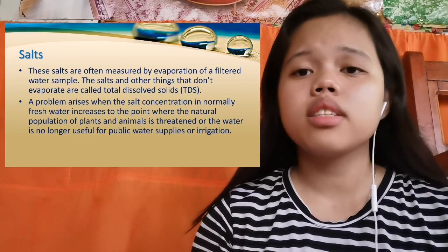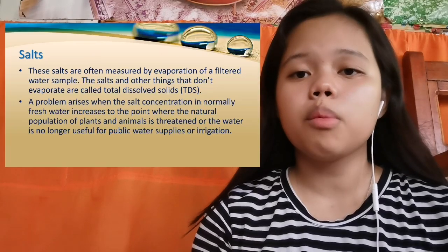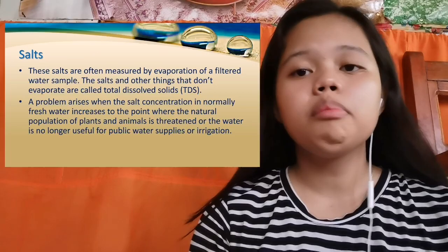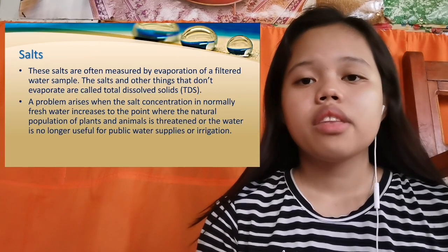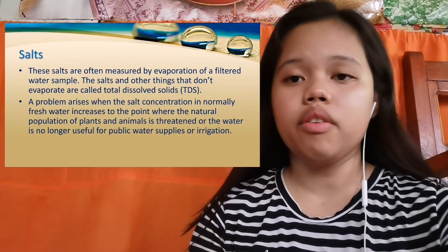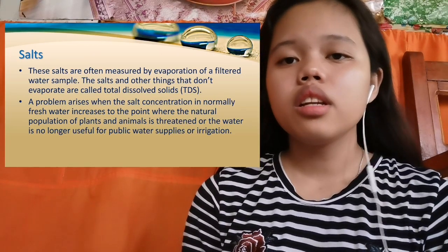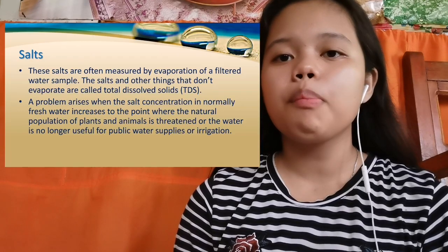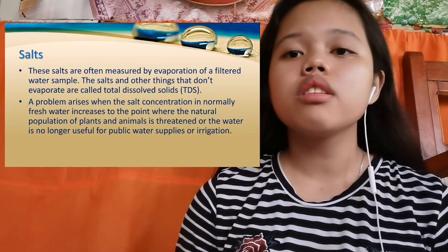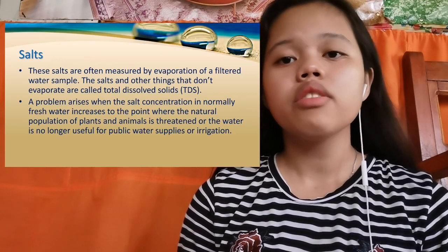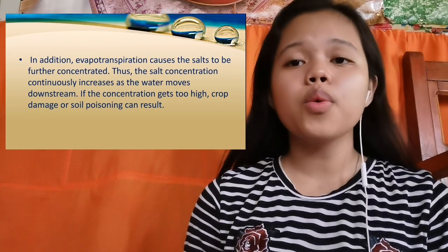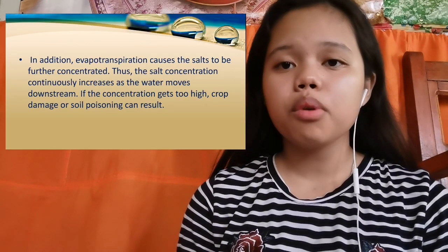A problem arises when the salt concentration in normally fresh water increases to the point where the natural population of plants and animals is threatened, or the water is no longer useful for public supplies or irrigation. In addition, evapotranspiration causes the salts to be further concentrated. Thus, the salt concentration continuously increases as the water moves downstream. If the concentration gets too high, crop damage or soil poisoning can result.